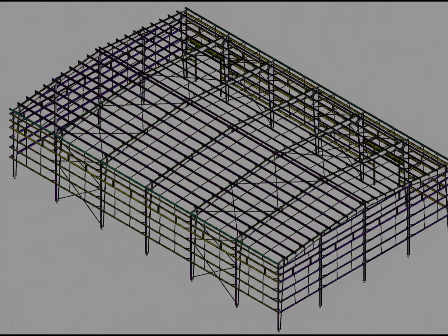First, identify the sag rod location in the 2D drawing. Second, identify the corresponding purlin or framing members. Third, locate the same framing bay in the 3D model. And finally, trace the slender rod member through that framing arrangement. This method is much more reliable than simply trying to recognize the member by appearance.